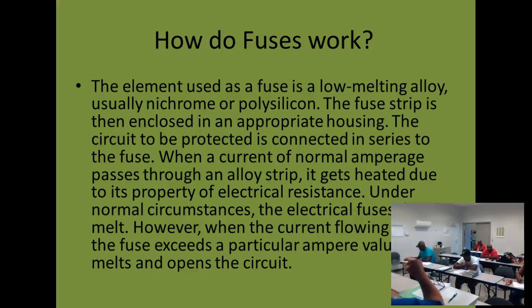You know, y'all are lucky. Most of y'all's meters now are fused. Many students have blown up a good meter, going, man, that was a $300 meter. You want to cut the power. You never want to put it on ohms and put it on a live circuit, okay? If you do, you might be replacing a fuse in your meter.